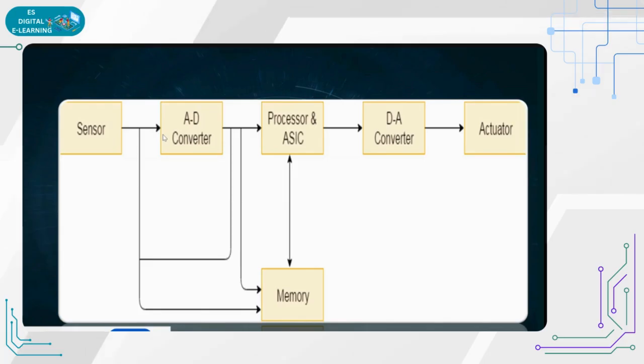So that analog will be converted to digital ones and zeros, analog to digital conversion. So the processor will understand only the digital. Based upon the sensor input, the digital input will be taken and processed. Once this is processed, some motors have digital and some have analog. If it is analog in nature, the digital will be converted to analog and sent to the actuator.